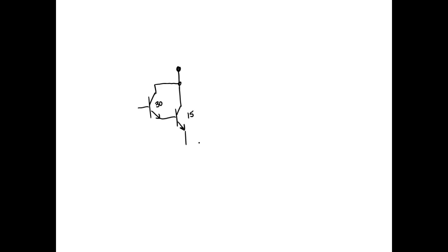450? How'd you get that? Yeah, you multiply them together because they're gains. Now I would have an overall beta of 450, which means if I put 1 milliamp in, I'd almost get a half amp out, right? Which is pretty good.